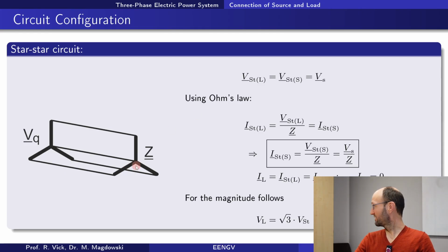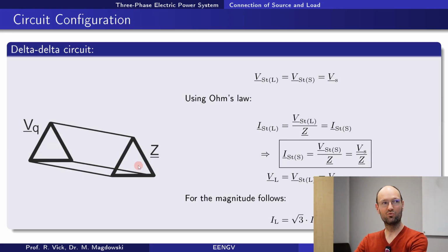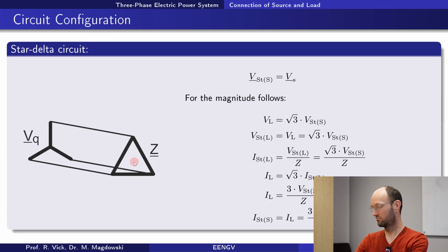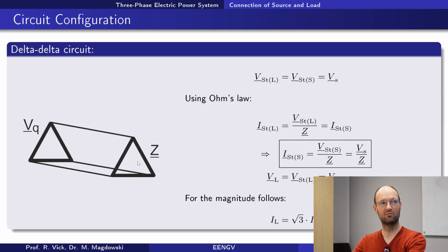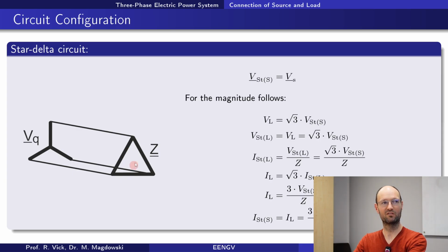We start with the motor in this connection, and then we switch to the delta. So if you have a large powerful motor, you would do it the same way. Start the motor in this configuration. Then the motor is not that powerful, but it will start to turn, and it will not use so much inrush current. And once the motor starts to rotate and the current goes down, then you rapidly switch the motor to this configuration to go to full power, but to limit the inrush current at the beginning. And so this is also what is done with motors.